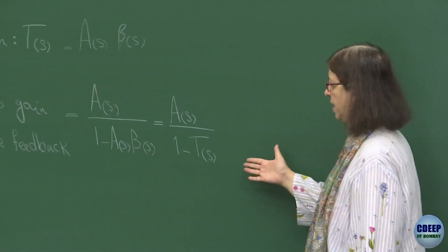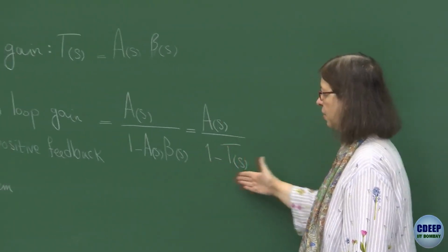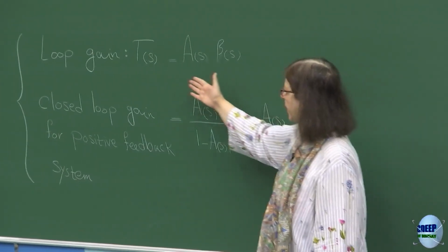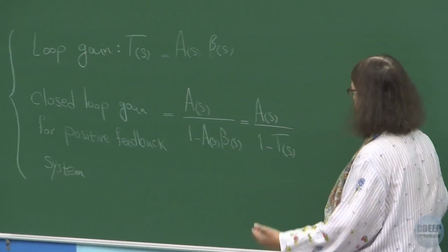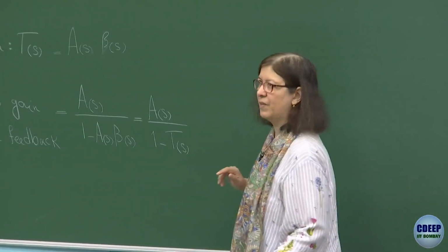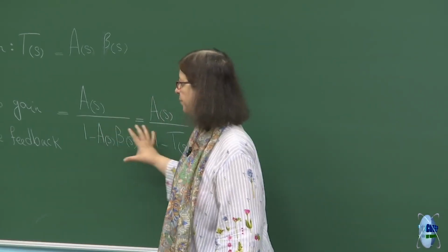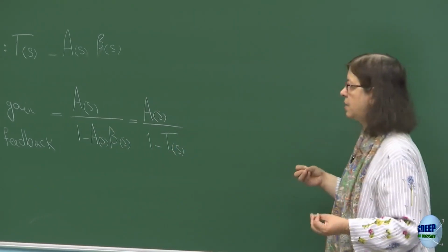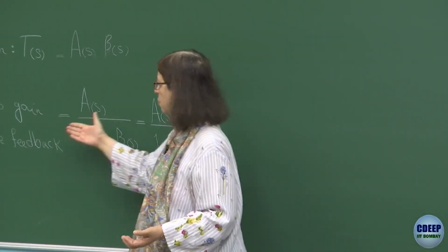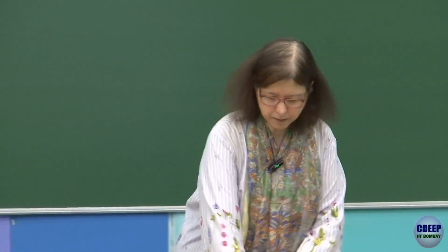So now, if you want to talk about the poles of this system, naturally they will be poles of the closed loop transfer function. If we were talking about loop gain, it is only loop gain. Now, notice the poles happen when loop gain is equal to 1. Therefore, if you remove the input and don't get any signal as an input, you don't have anything called the closed loop gain; it would be better to call it the transfer function.